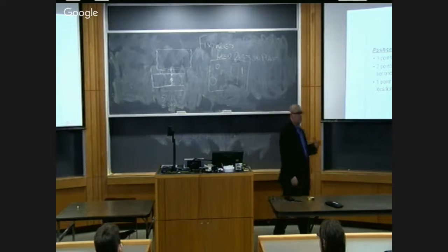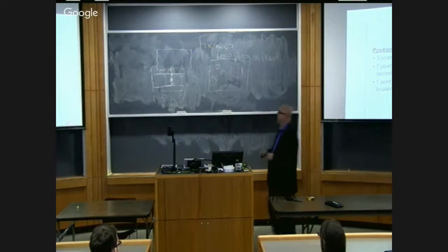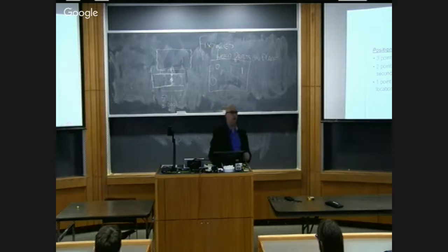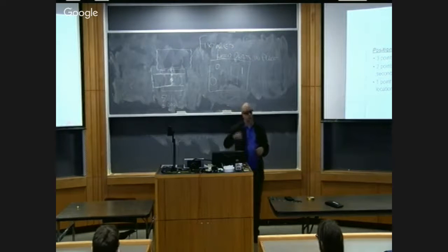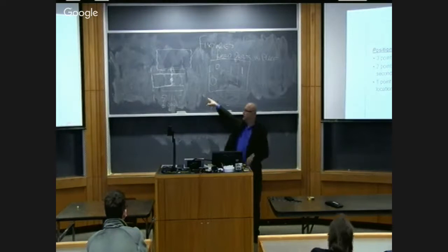So kinematics is the science of locating things. And so three points define a plane, right? So if I need to set the angle of something, I could have three balls, and it sits on those three balls, and I've got three points to define that plane. So I can change the angle by moving this one. Right, so three points define a plane. So what are the points in this scenario that are locating my workpiece so that I can repeatedly put it back in there? So I've got to locate the Z. How am I locating the Z in this scenario?